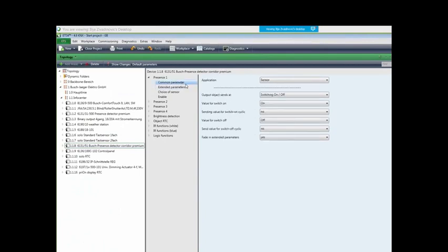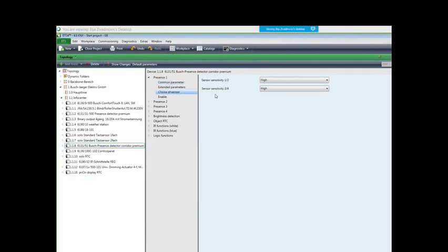You have also here the possibility, choice of sensors. Maybe you remember, as I mentioned in some slides before, typically our presence detectors do have 4 PIRs, 4 sectors, which you can enable or disable each single sector. Here is the difference to the corridor.